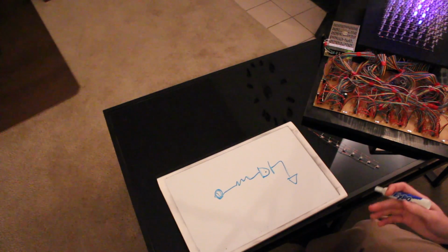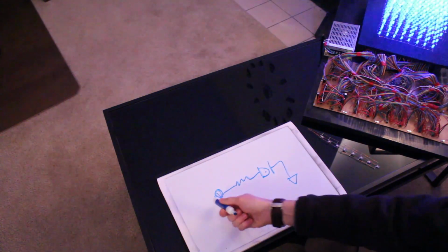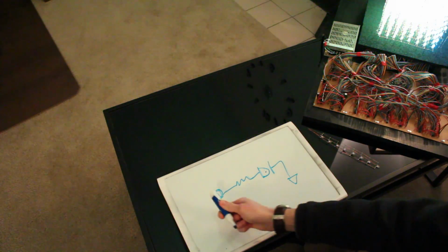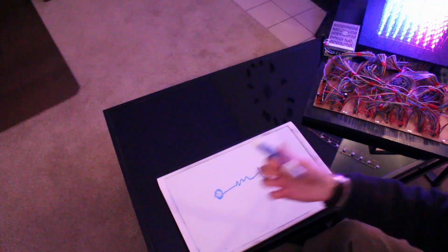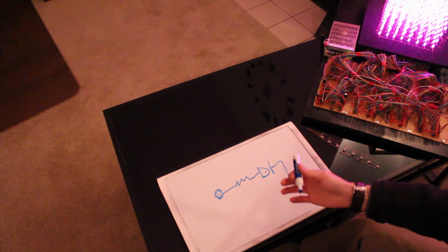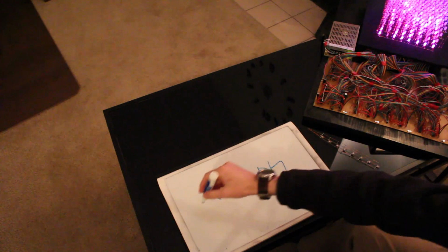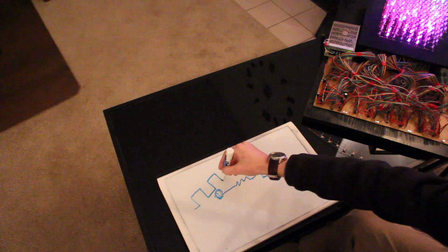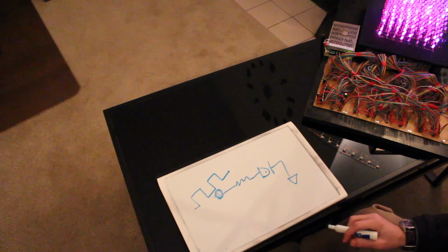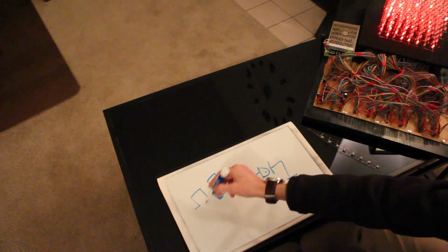That's its resolution. So if you wrote 255, this would be on all the time. If you wrote a 0 to it, it would be off all the time. Okay, so that's its duty cycle. If you wrote a 127 to it, that would be about half of 255, which gives you 50% duty cycle. So you would get a perfect square wave output on the pin, meaning you have equal parts on and equal parts off.